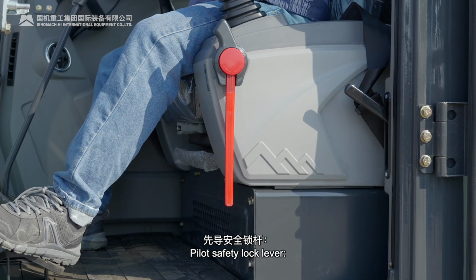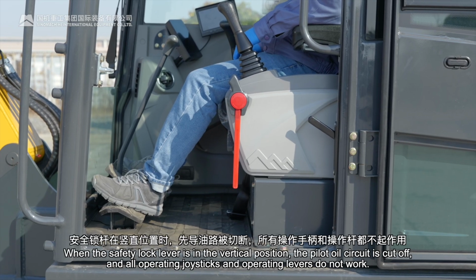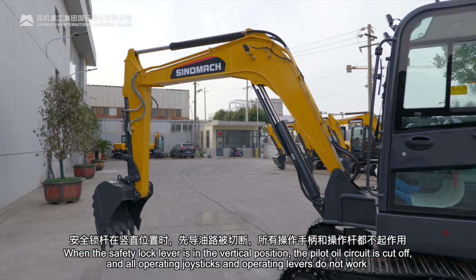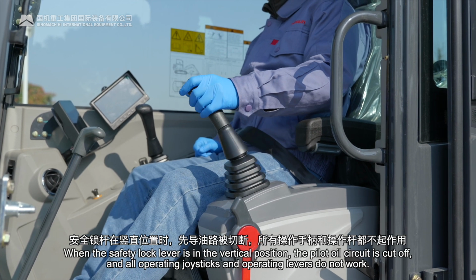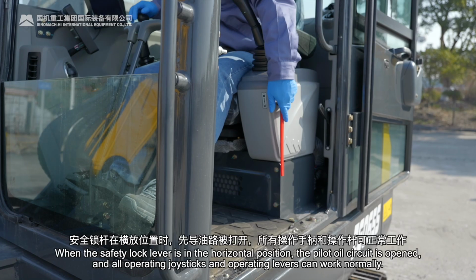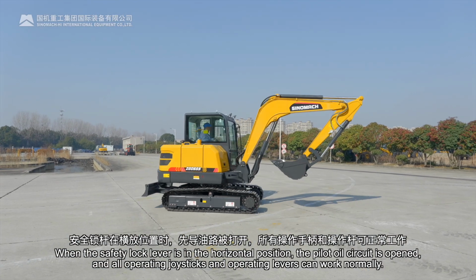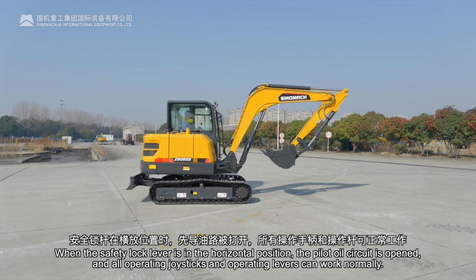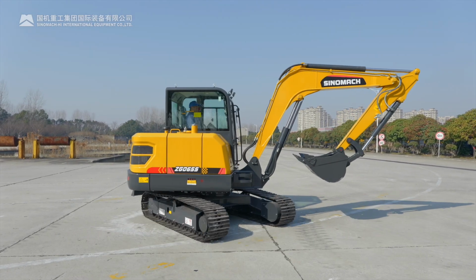Pilot safety lock lever. When the safety lock lever is in the vertical position, the pilot oil circuit is cut off, and all operating joysticks and operating levers do not work. When the safety lock lever is in the horizontal position, the pilot oil circuit is opened, and all operating joysticks and operating levers can work normally.